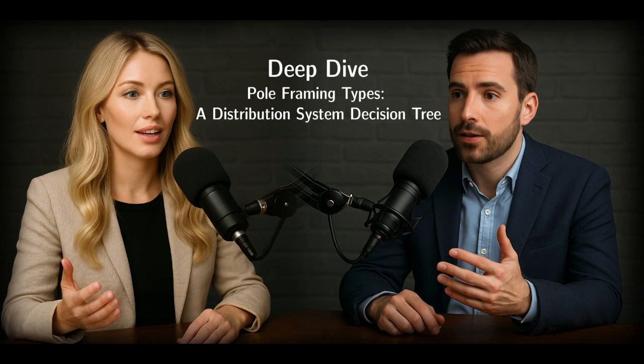Right. And what's critical here is how the conductors interact with them. With the suspension insulators, the conductors are literally suspended, right? They hang freely, allowing for movement. Dead-end insulators, on the other hand, signal a termination. The conductor actually stops at that point, pulling directly against the structure.